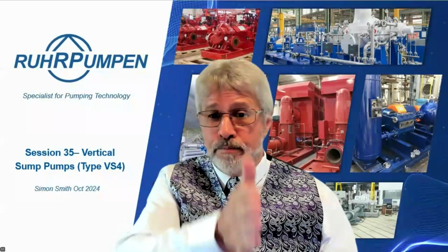Mayaresh Patil says, in the vertical pump, does minimum submergence vary with pumping liquid, or is it just a function of head and flow? Thank you. That's a good question. Yes, it's a vertical pump. If it's pumping a process fluid with a high vapor pressure, for example, NPSH might be an issue. And that is why the horizontal cylindrical tanks often have a boot in the bottom, a cylindrical boot at the bottom, so that the pump can be lowered further to get higher liquid levels in there to avoid NPSH problems.